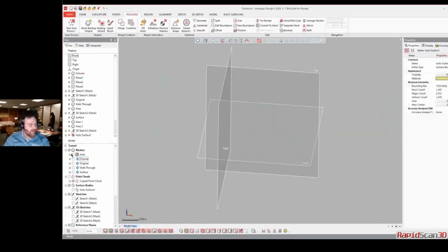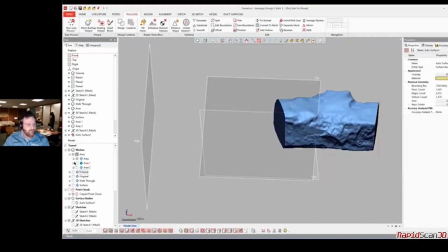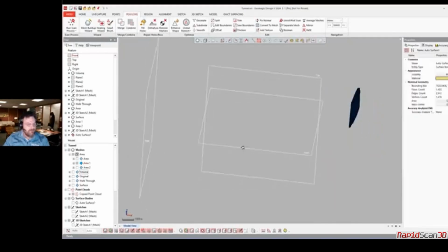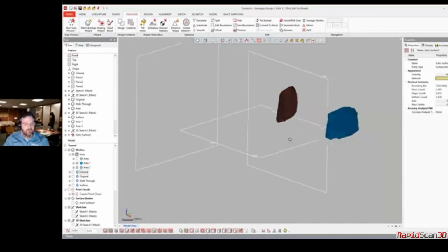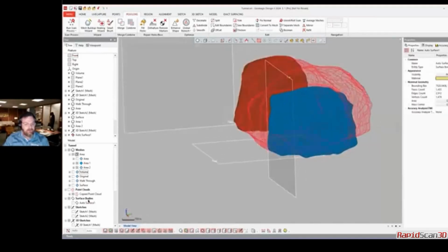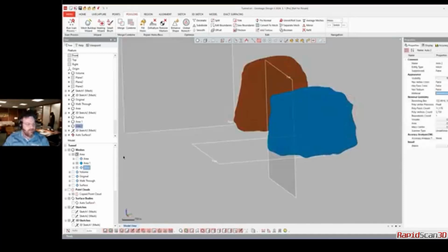But I've seen sometimes people want the area based on the cross sections. Sometimes you might want to divide up a section, and then take one little cross section. You see here that if I have these cross sections, I can come in and select that area number 2 and then calculate the area of just that cross section there. That is really valuable.